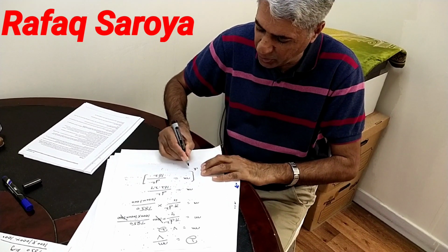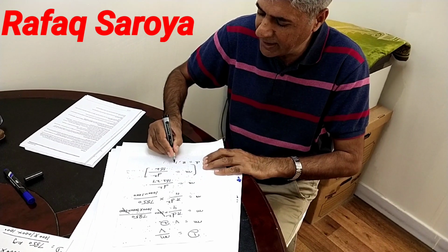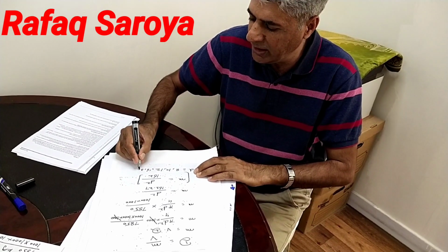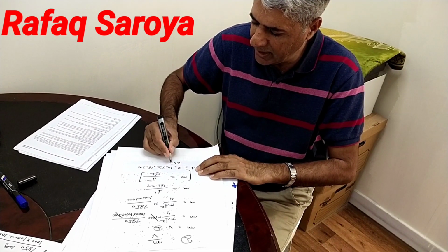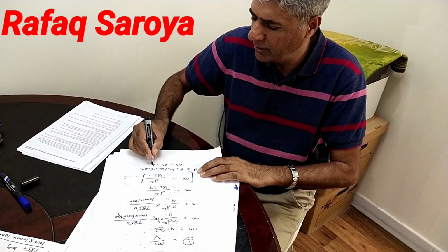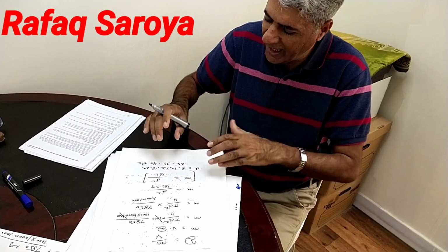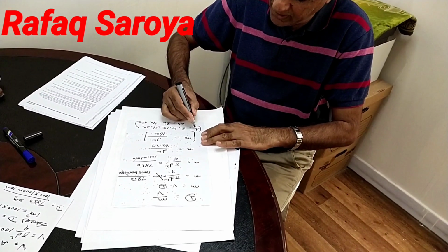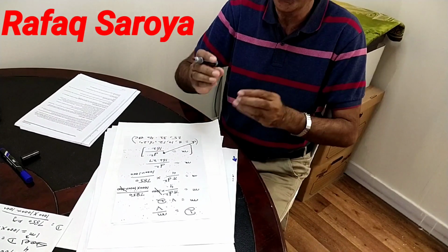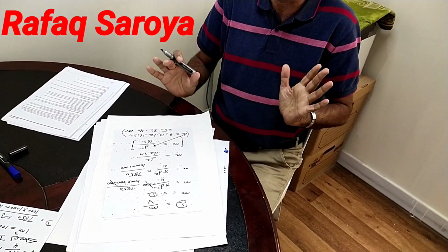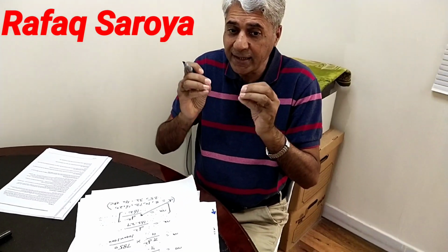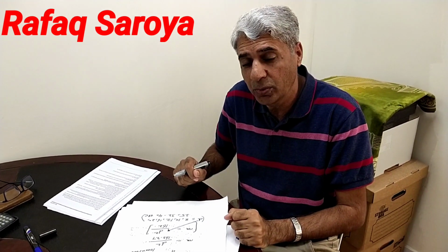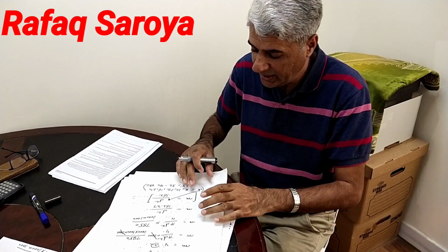As I have already explained to you, this can be 8, 10, 12, 16, 20, 25, 32, 40, etc. Any of the diameters mentioned over here, if this value of d is put in this equation, we can find out the mass per unit length. Unit length means what is the mass of the steel when it is cut equal to 1 meter length. This is the meaning of unit length.